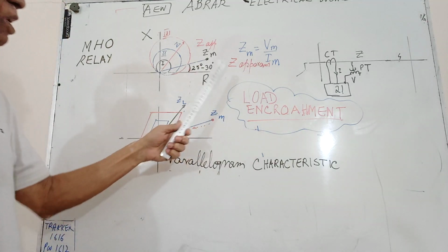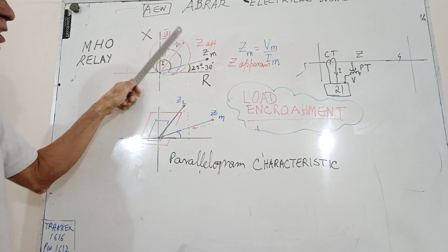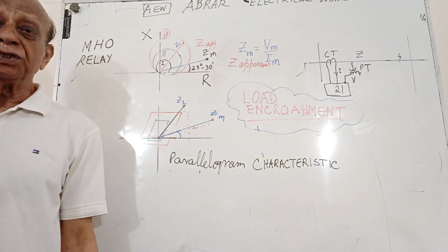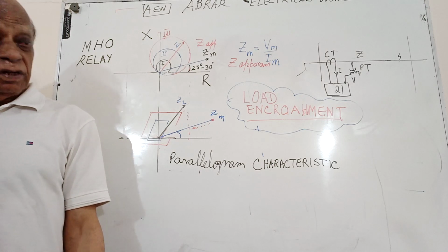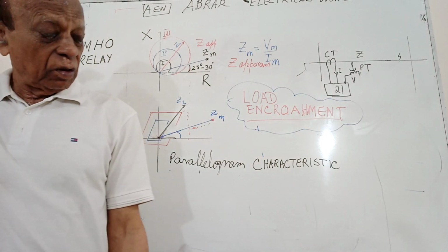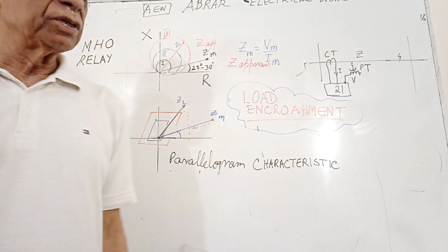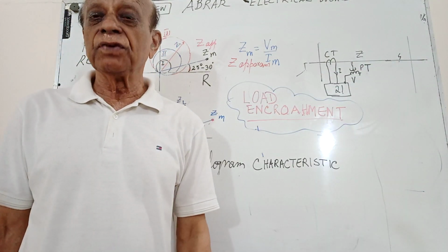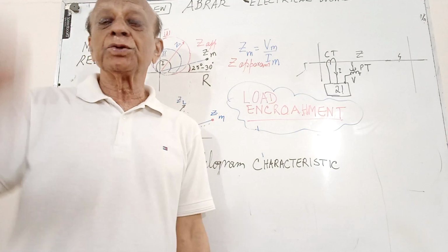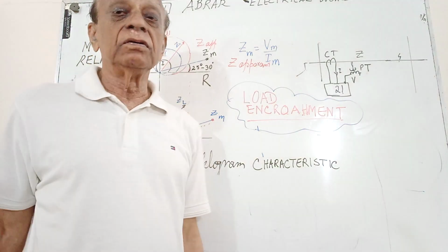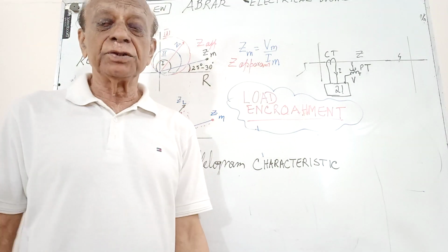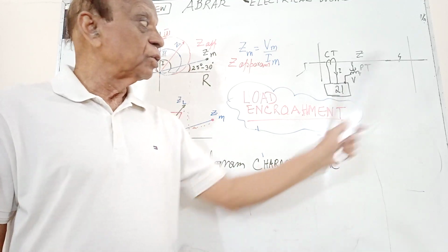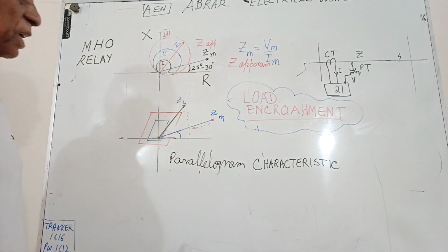So this one line is the calculated value of the impedance of the line on which you calculate the settings of the line, which is first the 80%, then 120%, and then the third zone, which is a very long line. The third zone actually covers at least 3 lines in a row, in series. So this is the recap.